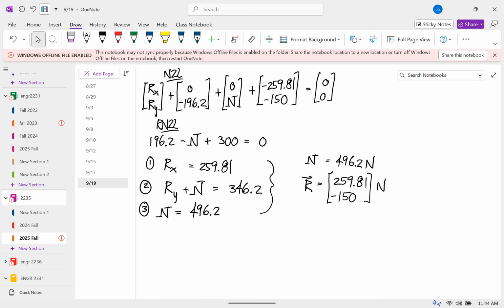In the problem we just did, if we were to take a more extreme version of it, we assumed the center of the circle was in the middle. What happens if we moved it very close to the point of the 300 newtons, and the 300 newtons was also perpendicular? Would that cause a greater moment about point A? You're right that it does have an effect on those moments. It doesn't have an effect on the forces, but that moment equation changes.